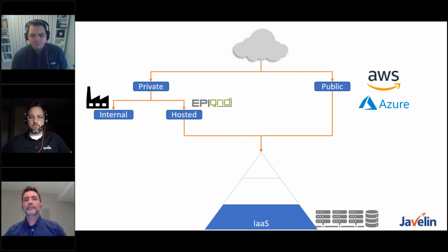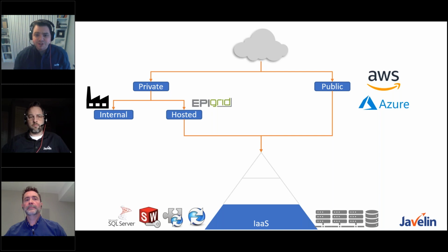So probably what you'd be most used to as a service name for this would be AWS EC2 servers. And that's kind of the gateway for a lot of companies where they've started with cloud hosting. This is where you would bring up a Windows server as an EC2 server, and then you would install your SOLIDWORKS PDM, SOLIDWORKS Manage, your Solid Network License Manager. And also this would be where, if you're using PDM or Manage, you would have your SQL server installed.